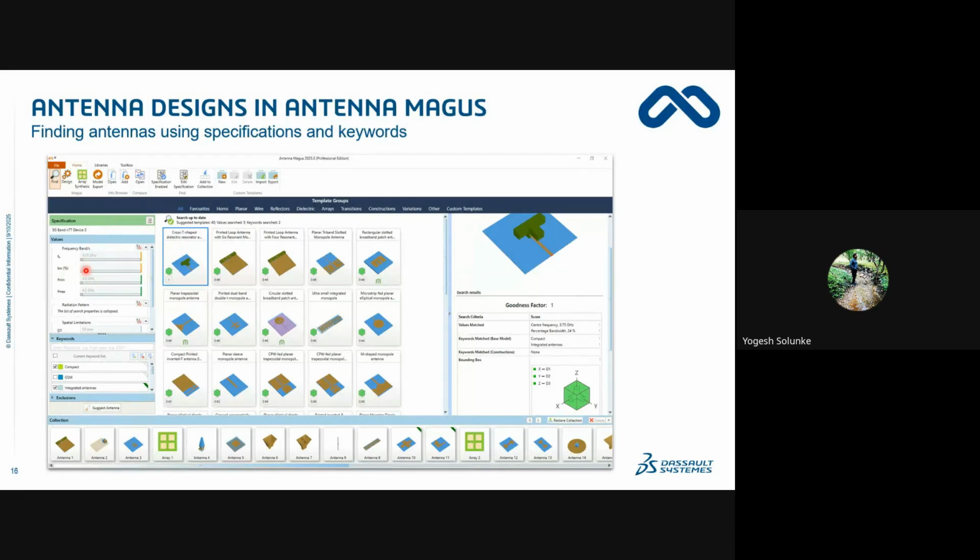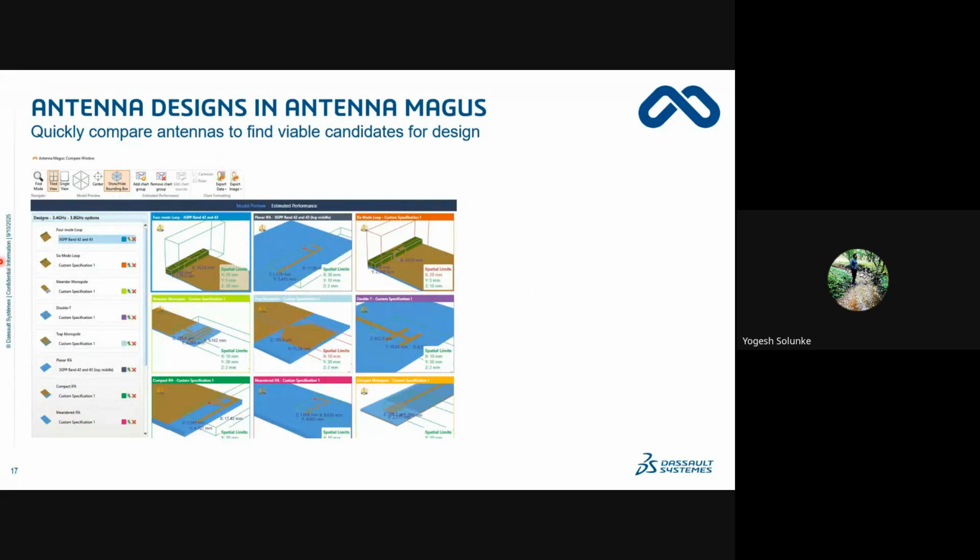So just give your inputs of operating frequency, get the 3D structures, export it to CST, and see the performance also. This way you can do some of the antennas I have listed here. Like if you want to work in the 3GPP band of operation, you have some different antennas. Again, if anyone wants to work in 5G waves or any low frequency application, you just need to set up that frequency band, and we can see some of the models will be already available over here.